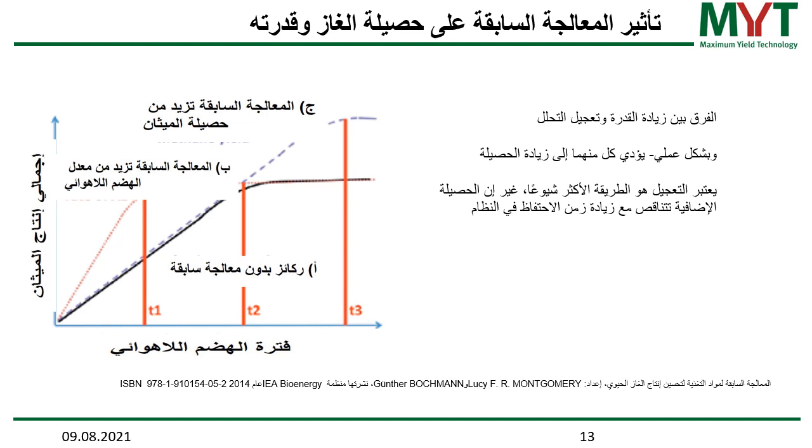In a technical application, an increase of the degradation rate of the substrate would result in an increase of the gas yield, because you have a defined retention time, let's say of 20 days. In this defined retention time, you achieve in your standard process 80% of the gas potential. So your yield is 80% of the gas potential. Now you accelerate the degradation rate, and the result of this will be that you get 85–90% of your potential at the same retention time.